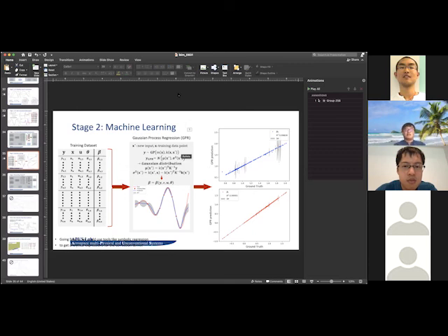So, Daniel, right now I'm working on transition. Could you elaborate on that? Have you considered transition in this hypersonic aeroelasticity, and will that have an impact on this problem? Yeah, definitely. Physically, if we consider transition, that will introduce a real peak in the heat flux on the wall in the flow field.